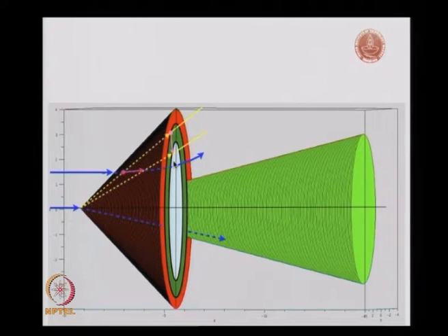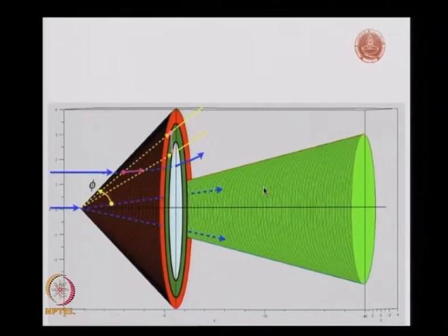Just wanted to remind ourselves. Now, again this is a streamline which is moving through the shock, and it is going on the surface of the cone. These are straight streamlines which are going on the surface of the cone. So for an axisymmetric case, you have the cone structure like that, you have the flow coming, and the flow equally diverges and goes past the solid cone here. This is what it looked like.